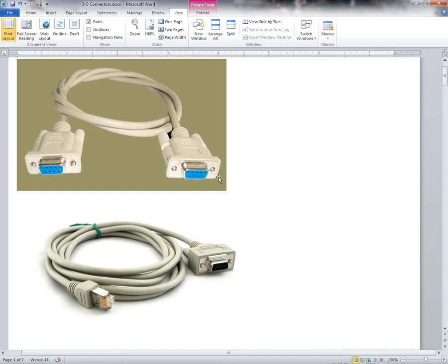It transmits 1 bit of data at a time, but it is full duplex. So that's excellent. It's also considered a reliable technology. It ranges in speed from 300 bits per second up to 115,200 bits per second, and that's the highest transfer rate that you can get within Windows. It uses 7 or 8-bit packets, offers flow control options and parity options, because once again it is a reliable delivery. You can't daisy chain serial, so it's point to point.